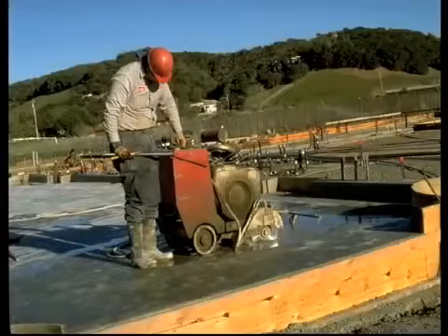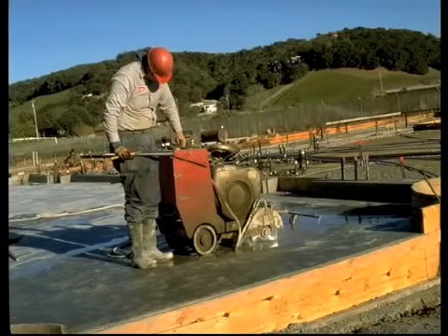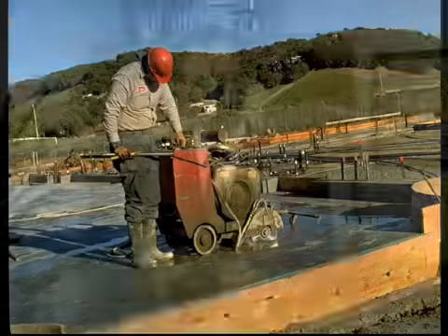We'll start with saw cuts. Saw cuts are good because they can be cut in straight lines and to the proper depth. The disadvantage of saw cuts is that they are usually installed the day after the concrete is cast. Cracking can occur that first night due to thermal contraction. So if you use saw cuts, make sure they are installed the same day that the concrete is cast. This is especially important if the weather is warm or hot.